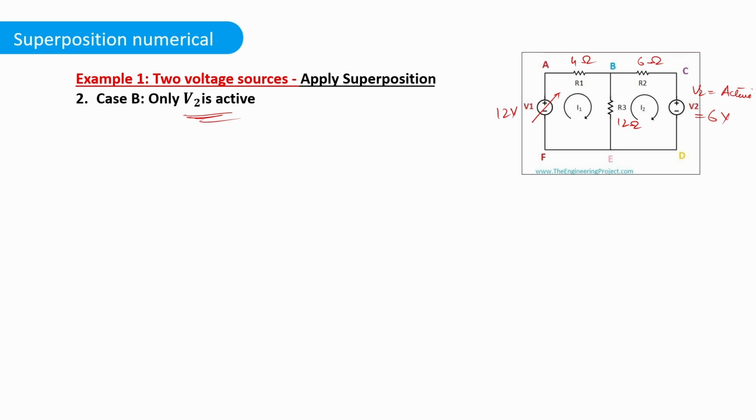Current sources are always replaced with open circuit. So let's begin with the KVL in each loop. So this is the first loop. So let's apply KVL in the first loop. Since this is short circuit, it will actually have no influence now. This will be 0 volt. So we can directly go to this one. Voltage across R1 plus voltage across R3 is equal to 0.